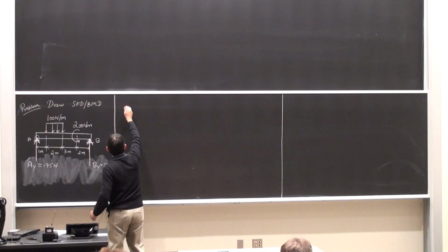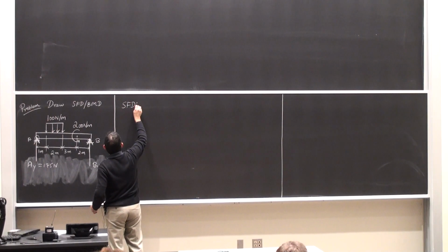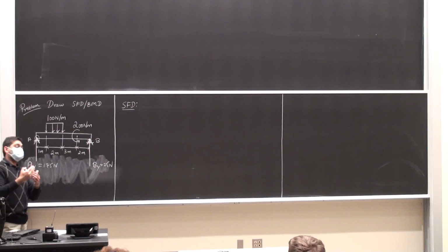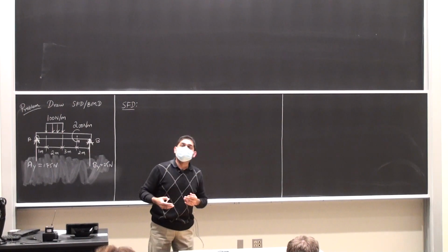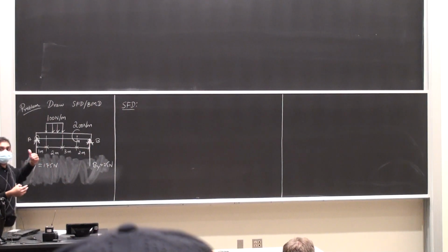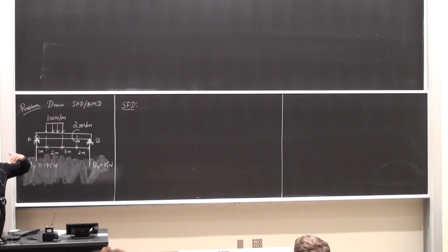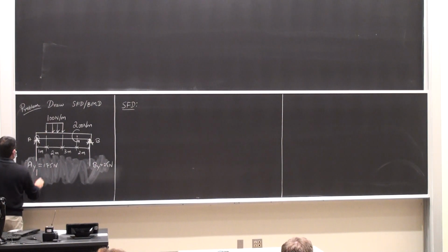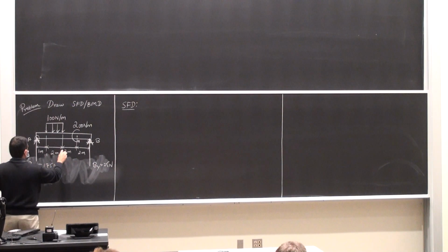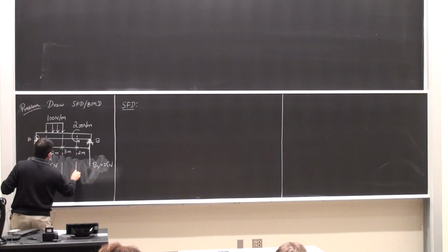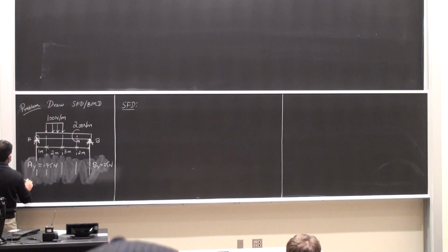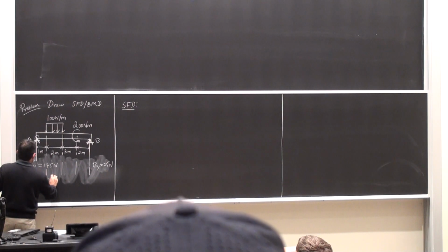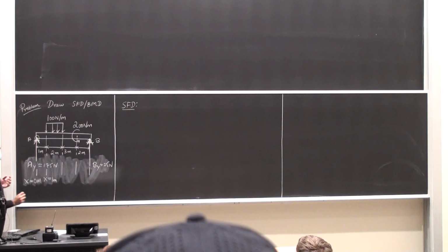So shear force then. What are my locations? My locations of interest are where there are loads acting or where there are load changes occurring. Okay, so I start off with X, positive from left to right. Y positive is from bottom to top. This location is 1. X is 0 meters right at the beginning. X is 1 meter right there.